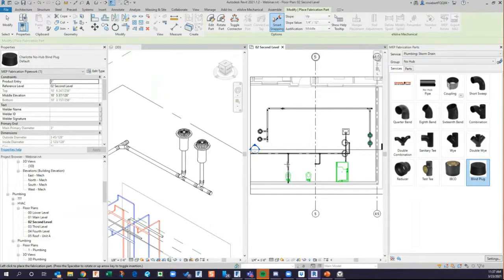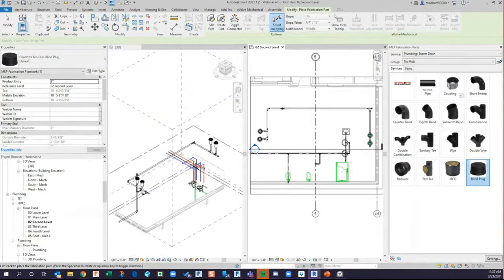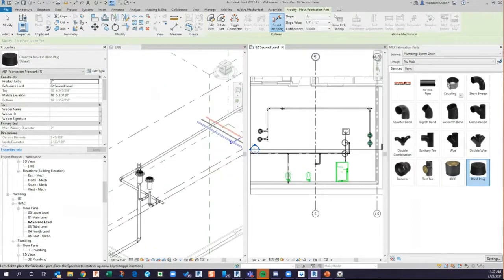So I love being able to use design to fab to convert any sanitary pipe. But the one thing you have to remember is sanitary pipe is always, in most cases, going to come over from the engineer in a flat mode. If it does come in a flat mode and you're going to need to do a little work, sometimes what I will do in my practice is leave the pipe exactly the way the engineer drew it, but I'll come through and start looking at how I'm going to reroute this pipe to save a couple fittings. As you can see on this route here, I took out 2 90-degree short sweep elbows going up into my storm drain.